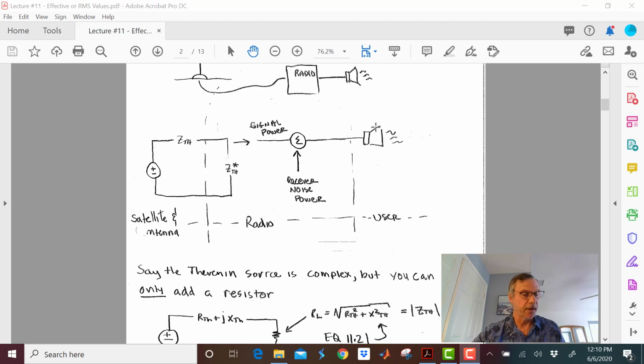One final cool thing for your job interviews is antennas are typically designed so they present a 50 ohm Thevenin impedance. So typically you can treat your antenna as a resistive Thevenin source at the band where you're using it. That's just a nice little piece of information to have.